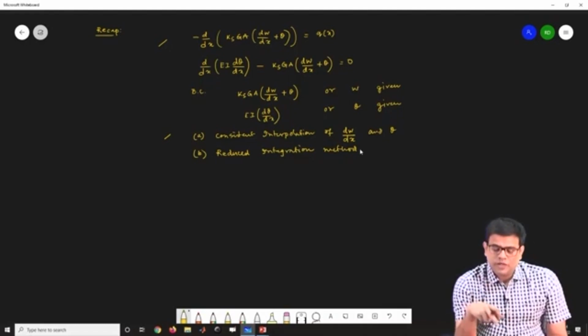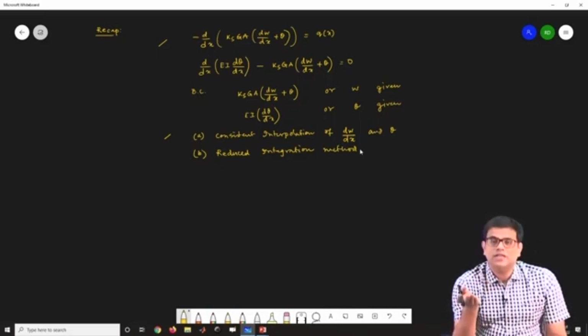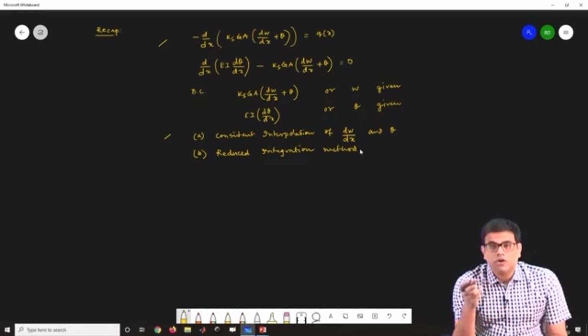Now there are four boundary conditions here. These four boundary conditions are not due to a fourth order differential equation. One has to look carefully at these differential equations. These equations are second order equations. There are two differential equations, and the highest derivative present is of order 2. That is why 4 boundary conditions are required. On the contrary, in the Euler-Bernoulli beam theory you need 4 boundary conditions because a fourth order derivative exists, which is EI d to the power 4 w by dx to the power 4 equals q.